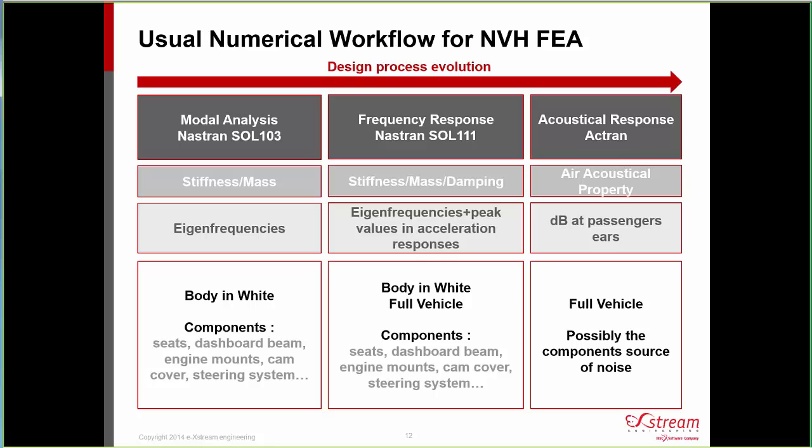At this level, the equation changes a little bit because we don't only care about the stiffness behavior of the material and the structure, but also about its damping behavior. And here there is a new output compared to the modal basis, which is of high interest: the peak values in acceleration response. To evaluate peak values in acceleration response correctly, we need to predict correctly the damping behavior of the material.